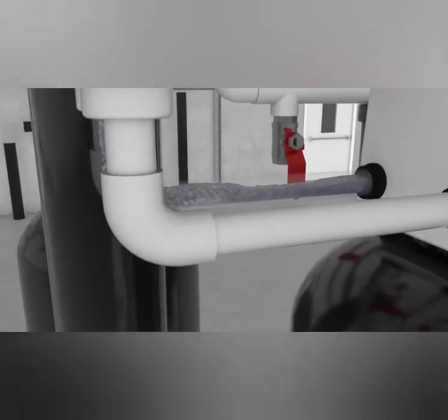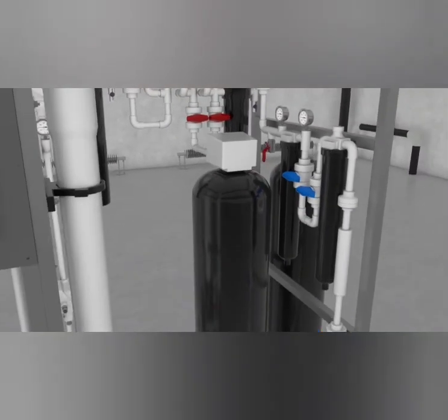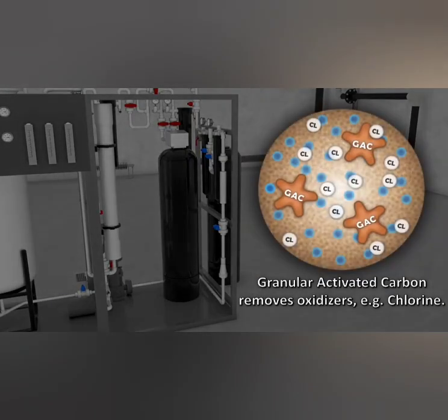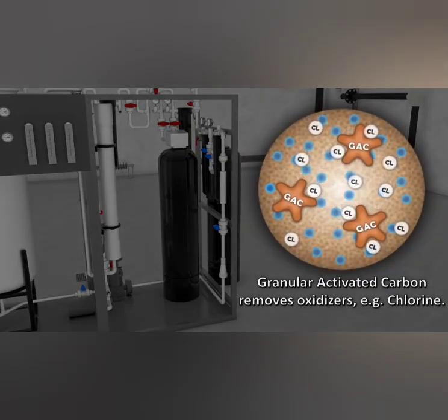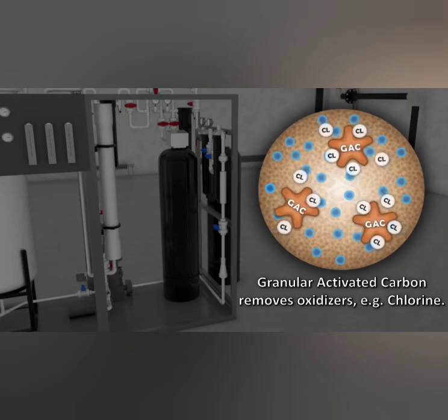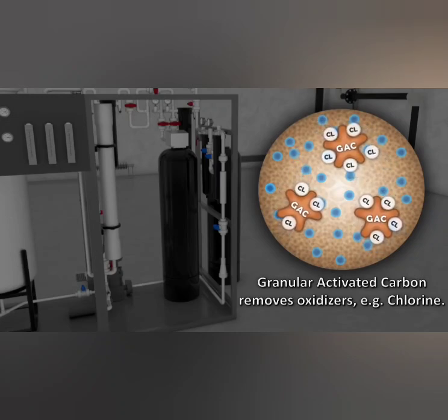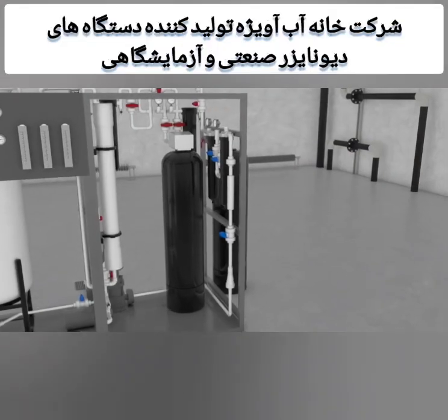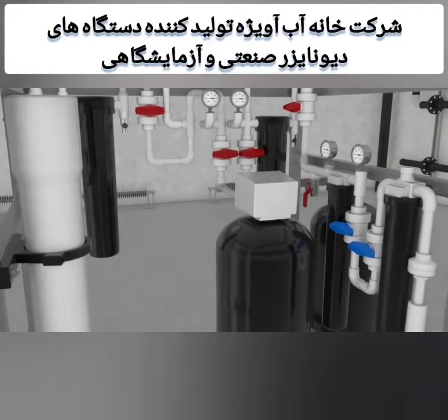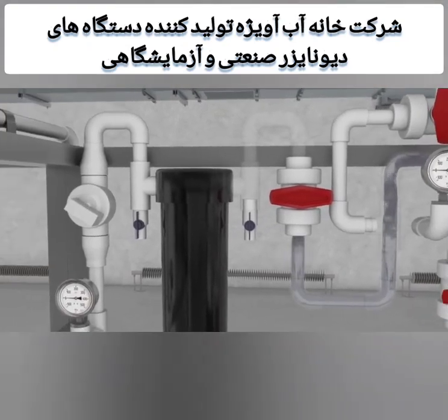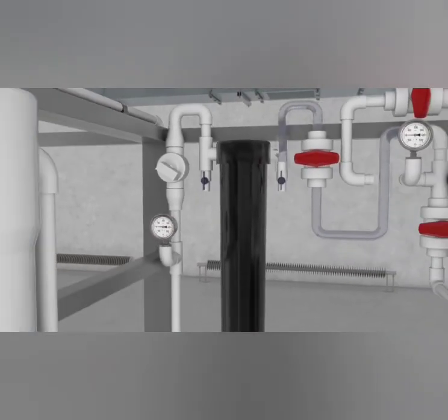Reverse osmosis is sensitive to oxidizers such as chlorine, typically found in all city water sources. Therefore, the process and water RO water system includes granular activated carbon, commonly called GAC. The GAC is an absorbent and will reduce the levels of chlorine being sent to the RO membranes. The effluent of the carbon column passes through a higher micron capture filter to capture any carbon fines that may have been released from the vessel.